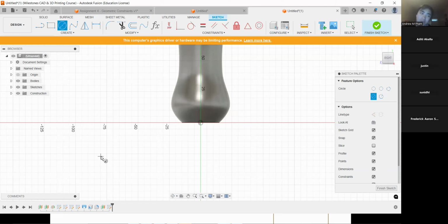So the reason why I do it is it gives me a little bit more control and allows me to confirm certain things. Because sometimes you might draw something that looks vertical and it very well could be, but it may not always add the constraint automatically. So what I like to do is draw something at an offset and then add a constraint to lock it all in.